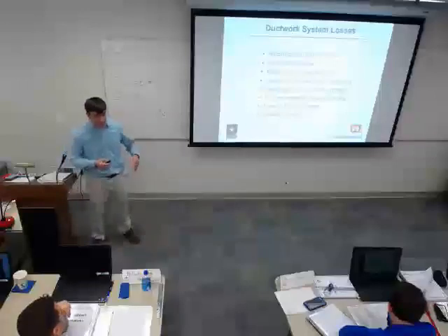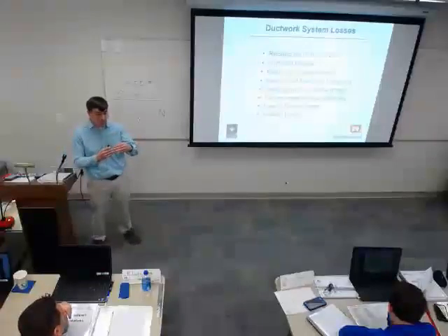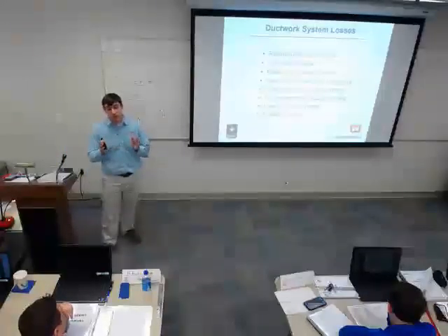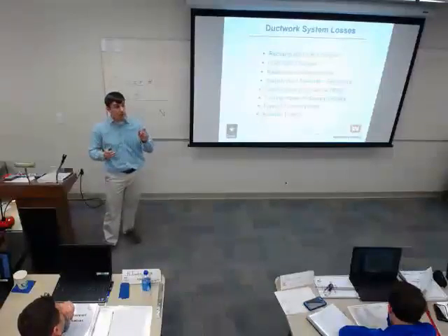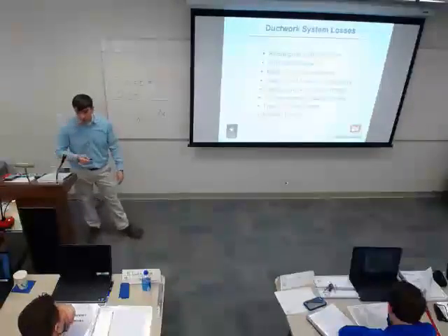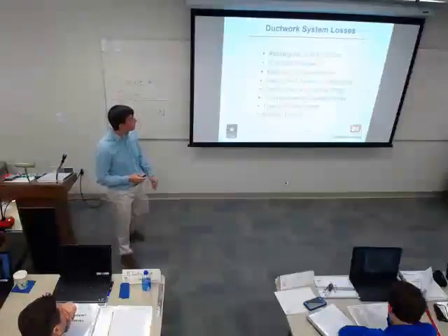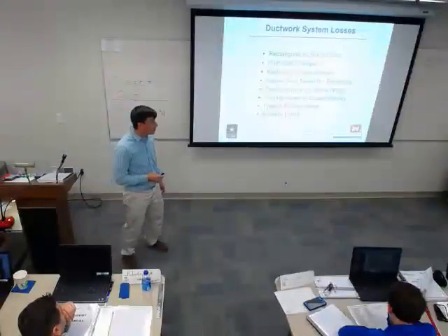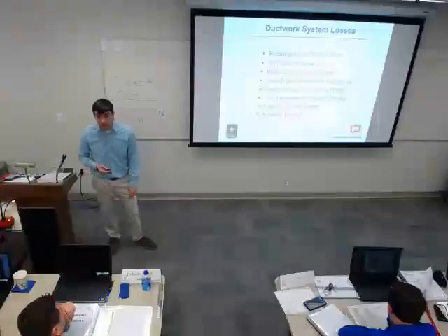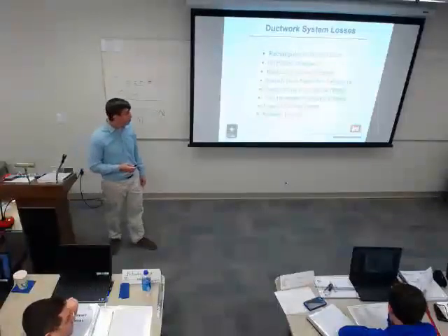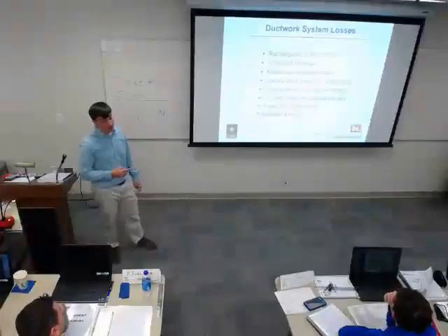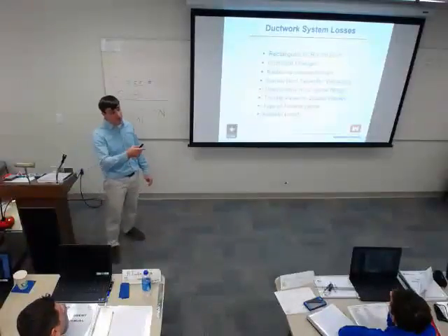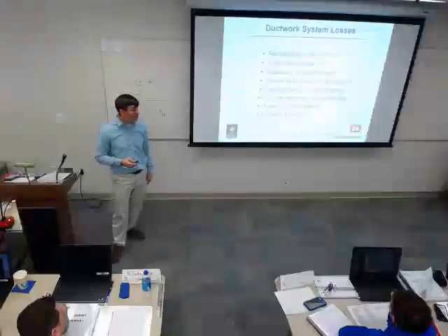The key takeaway on acoustic lining: if a designer shows a dimension, you need to check your drawings, because that should be the inside clear dimension. So your duct would have to be bigger than that to allow for whatever 1 inch or 2 inch of acoustic lining inside of it. But if I'm not mistaken, the HVAC UFC says not to do it. You want STCs. You might find a situation where you have to have it for sound purposes, but in general, the UFC says not to use it.